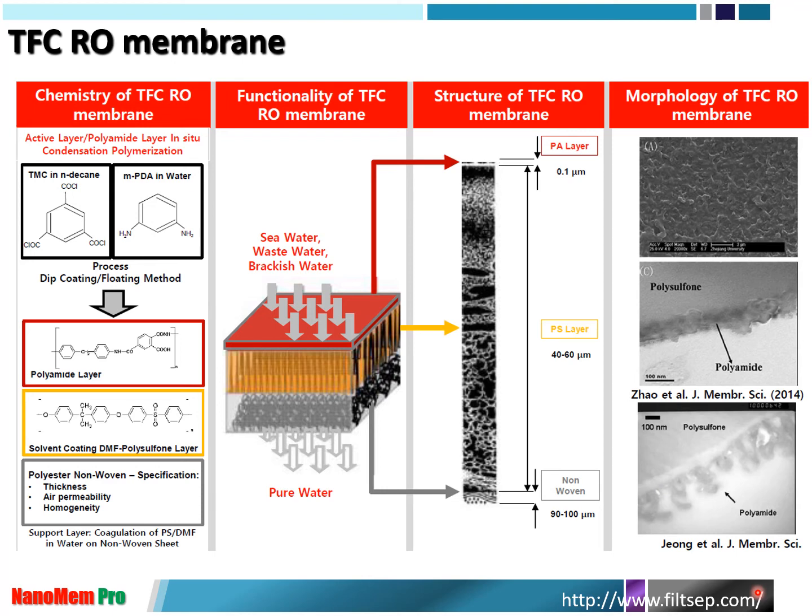This can be nano-sized: a water molecule is around 0.3 to 0.4 nanometer, and sodium chloride is around 0.6 nanometer. So you have to separate sodium chloride and water, which means the polyamide pore size of about 0.5 or 0.6 nanometer will separate the water from sodium chloride.